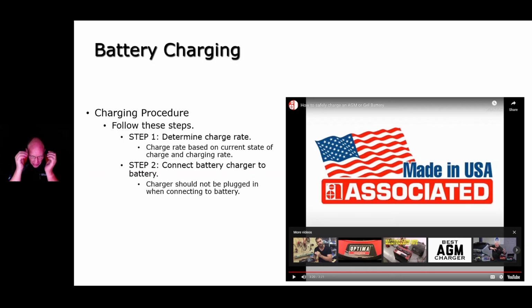So that's where I've learned that some of these cheaper chargers are good, because you can throw that cheaper charger on there and it doesn't care. It's still going to supply power to it. It's going to get that battery back up over a volt. And once you get it back up over a volt, you can take that cheap charger off it pretty quickly at that point and put the smart charger on it and get the smart charger to kick in and start to recover that battery.